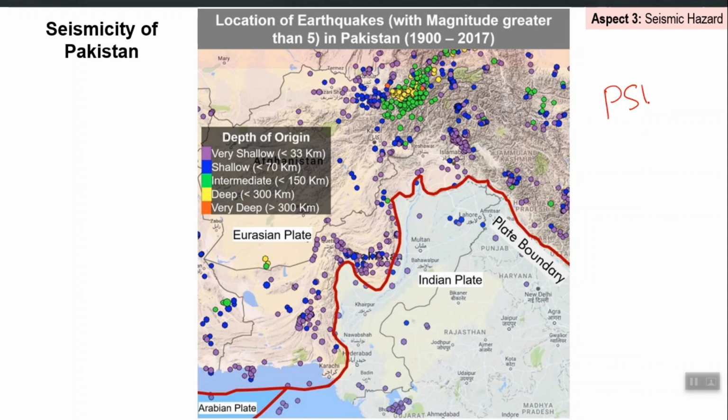This process, PSHA, is the state-of-the-art procedure nowadays. Previously we used to have deterministic seismic hazard assessment, DSHA, but nowadays we use this one. And within PSHA also, nowadays there are several approaches. In one line, this is a process which, in a probabilistic framework, performs the analysis on all of the previous data available for a particular study area, and as a result of this analysis you forecast what level of a particular seismic hazard parameter is expected at that particular study area, right.